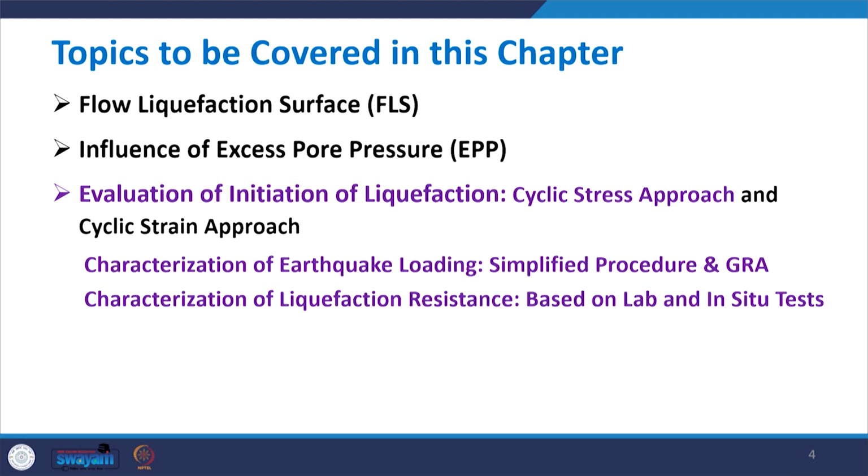Today we are going to talk about the 3rd topic, that is evaluation of initiation of liquefaction, which can be understood using 2 approaches. One is called the cyclic stress approach and another is the cyclic strain approach. The cyclic stress approach we will discuss in much detail. In this approach, we need to characterize the earthquake loading as well as the liquefaction resistance in the same terms.